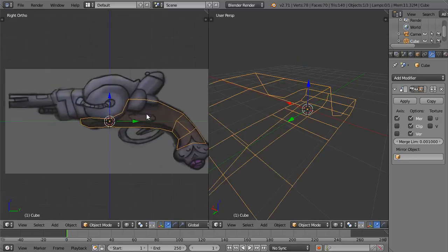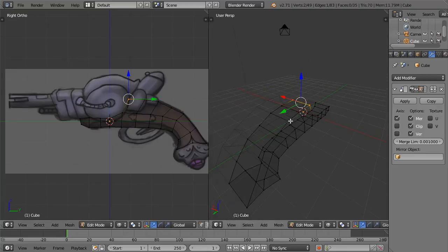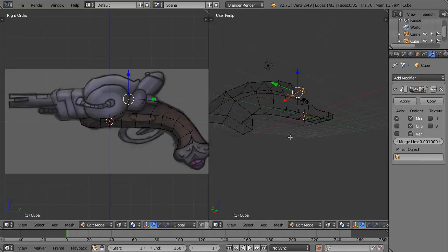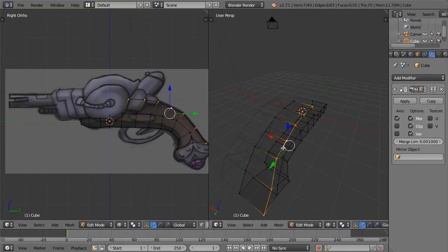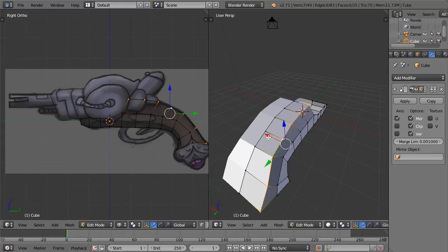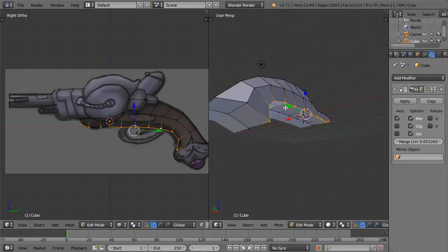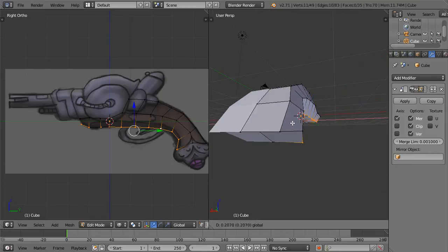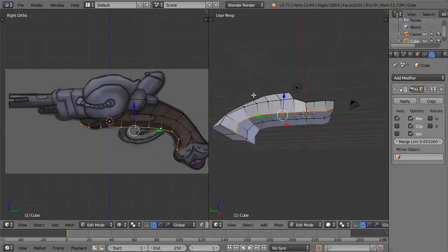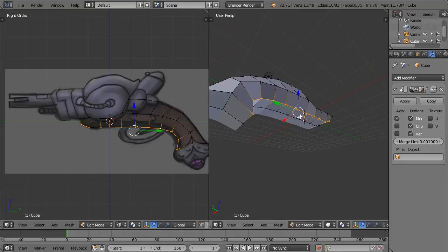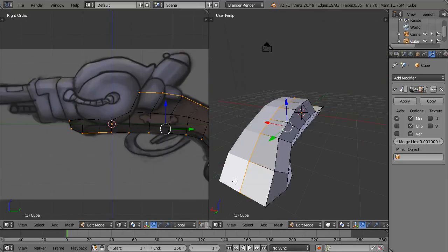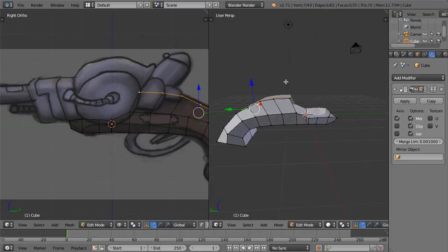All right, so we have our fancy little mesh right now, and I'm actually gonna kind of pull the points in a little bit. So Z is to shift between visibility modes, so like wireframe, which I've been on, and shaded mode, so we can kind of move points around, and I do a lot of point-by-point modeling.